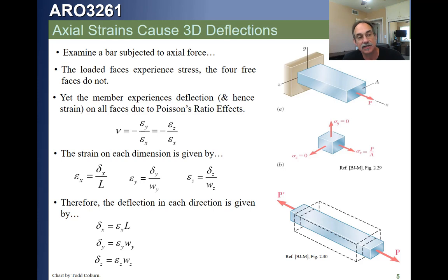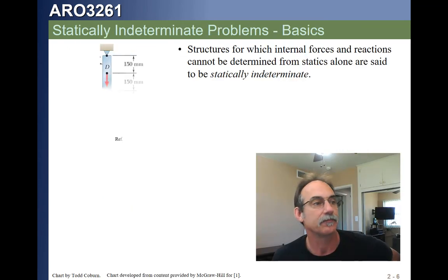If we have a single axial force like shown here, we can directly calculate the deflection in that direction, PL over AE, and we can use the strain from that in order to determine the changes in dimension in the other two directions.